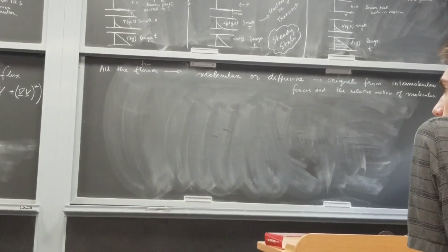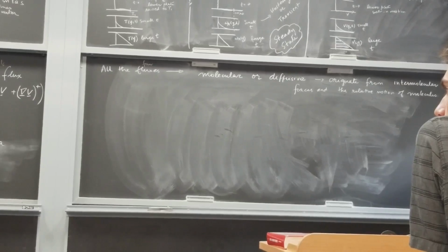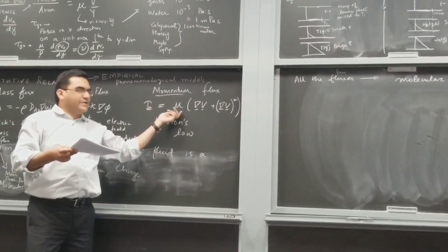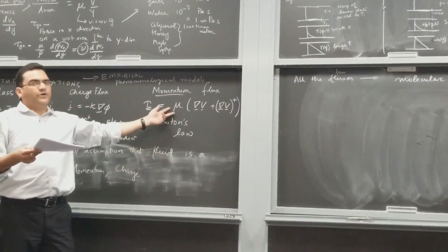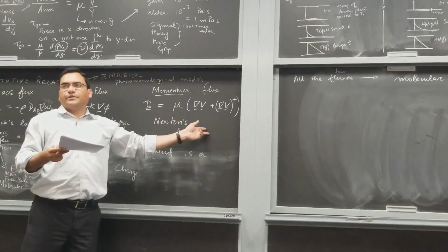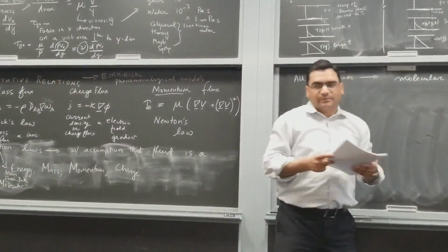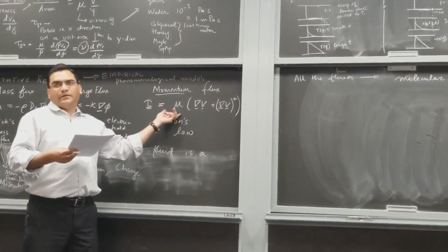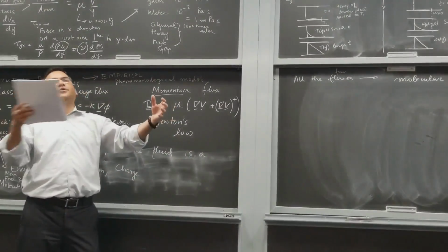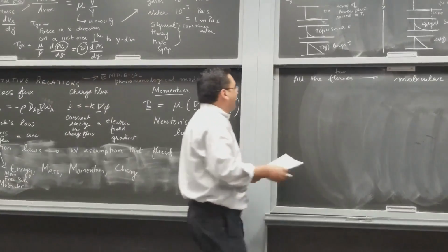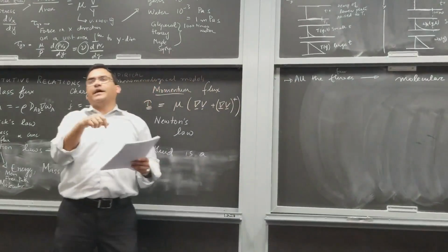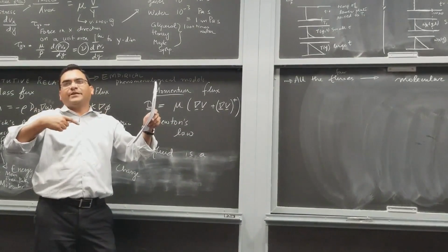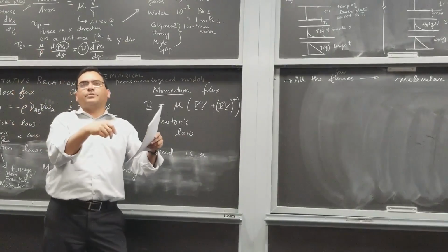How far it can be transferred is more or less determined by the property viscosity, which in some sense dissipates this. So it's a dissipative form of transport. And how quickly it dissipates depends on whether you're looking at water or gas or a higher viscosity fluid. So if I wanted to design some way of stopping a fast-moving train, one way would be to have that train go into a very viscous fluid. But I don't think anyone would like that. Alternatively, you can have the fast-moving parts of the train moving in a rheological fluid. When you apply a magnetic field, it can go from being liquid-like to solid-like, and that can stop it relatively quickly.